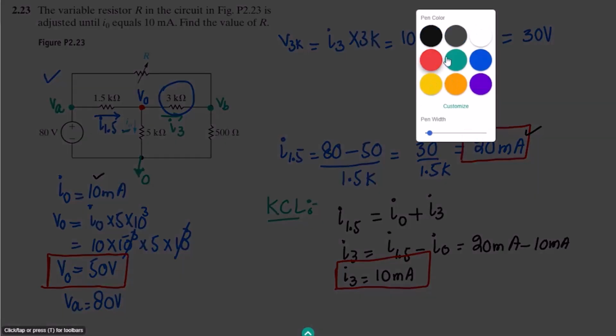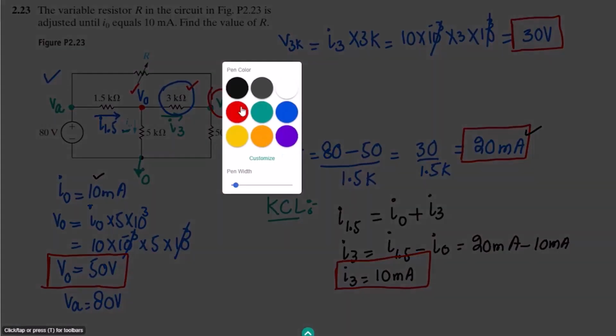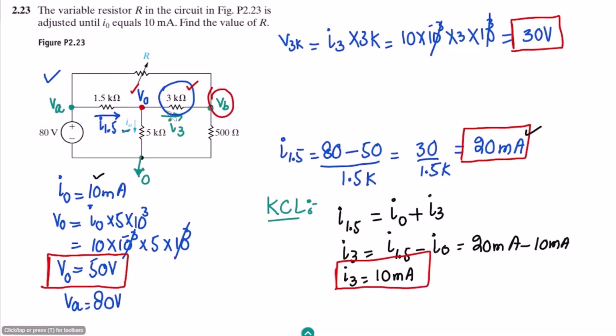Okay, so this is again the voltage which is known. So now we know this voltage, we know the consumed voltage as well. We can very easily find out this voltage now. So from the potential difference formulation, we know that V naught minus VB, which is the potential applied and the potential which is remaining, is equal to the consumed voltage, which is across this 3K.